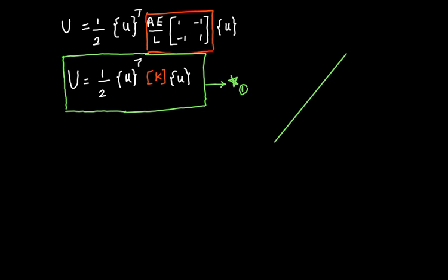All right. So now we are going to derive the expression for strain energy for a truss member. So here we go. Let me first construct a truss member. It's inclined, and I have to be very careful when I say that this is an inclined structure, because I have to mention the angle. So let me mention the angle here.